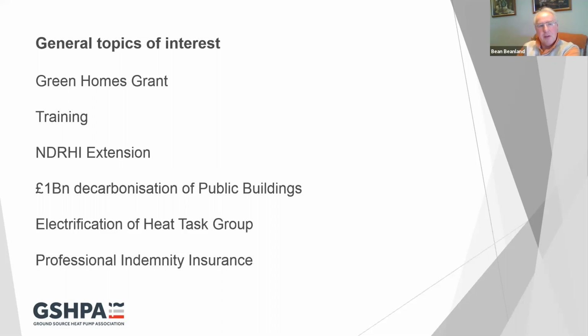So there's a course being developed to effectively put the same requirements on fossil fuel installers that have always pertained to MCS certified installers. So heat loss calculations to the standard, room by room emitter sizing, pipe sizing, pump sizing, hydraulic balancing, all the things that MCS certified installers have been expected to do for years are now going to be included. And critically, the boiler manufacturers are supporting this. I think they've got to, because it's the last hurrah from their perspective.